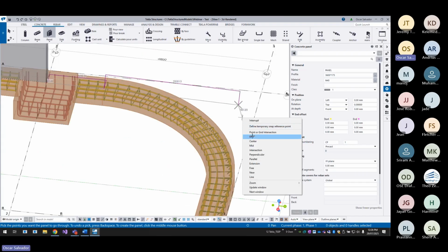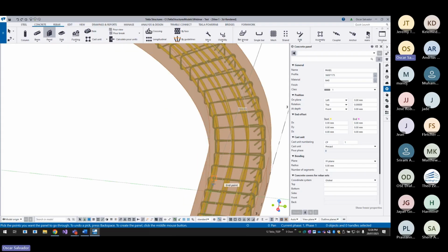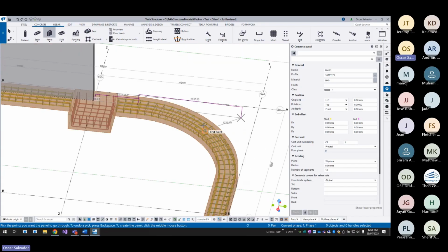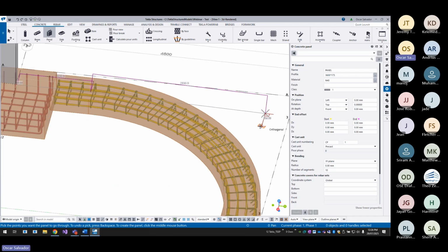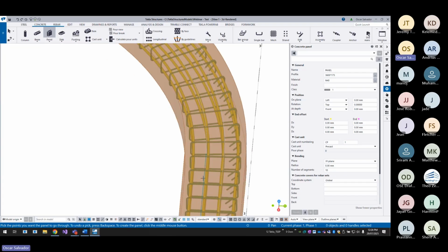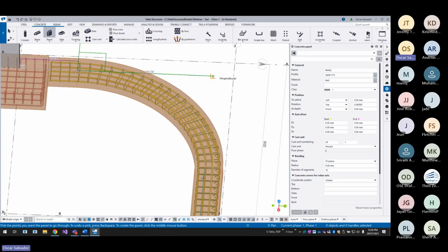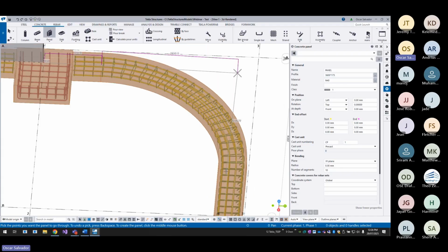Then I will right click again and press end, and look for this end point here, which should be the same as the 29. That shouldn't be 2930. Let me press the backspace. The perpendicular again. Yeah, 2912.5. Then press the end. We should have the same.